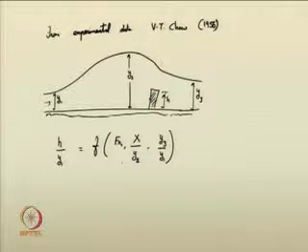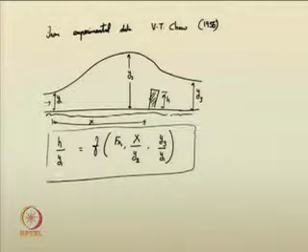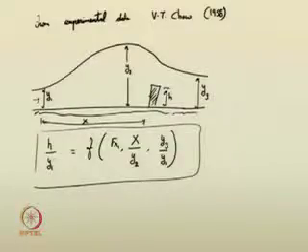What is capital X here? It is the distance from the beginning of the jump location, the toe of the jump, to the toe of this sill. So, this distance is called x. Like that, from the experimental scientists it has been observed that the ratio h by y 1 is always a function of the Froude number, x by y 2 and y 3 by y 1. Once you incorporate these mechanisms, the design of the sill will be appropriate, and you can design the sills in a better way.